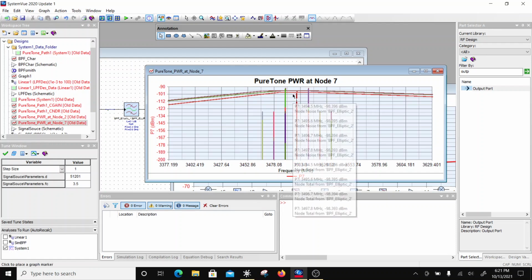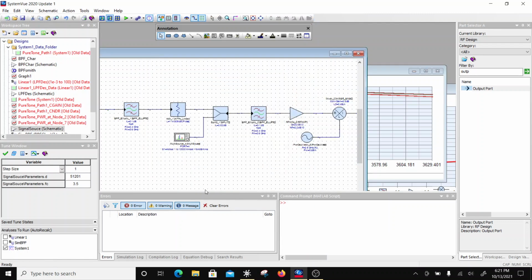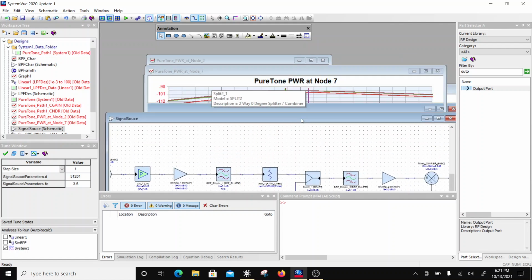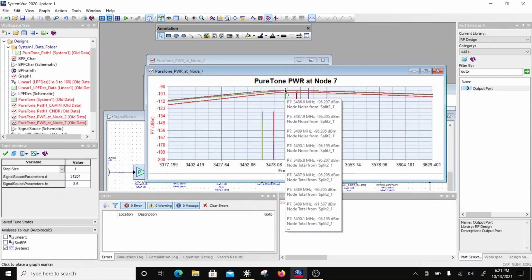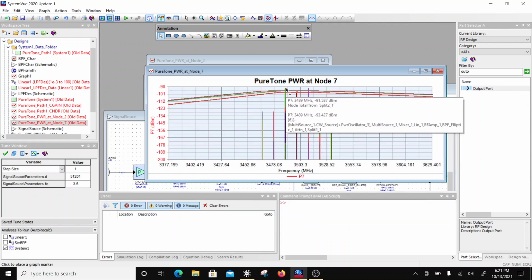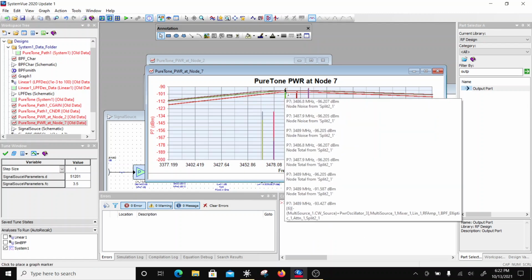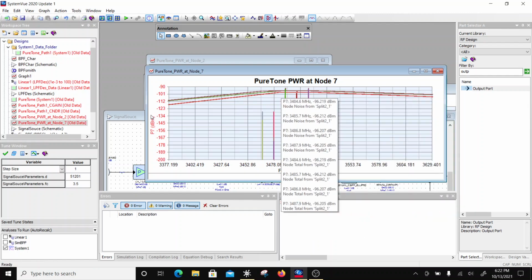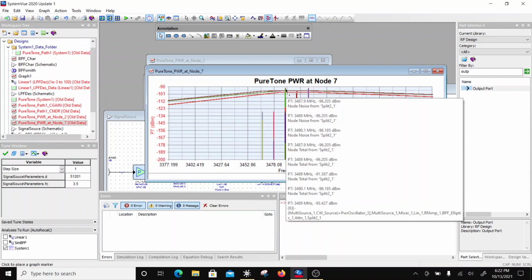And to improve this, one more way would be to have higher directionality antennas. So we have to change the antenna gains, and that will also come into the picture. If you do that, the sensitivity numbers will improve if the gain of the antennas is increased, right? So then this can go way down, minus 106.